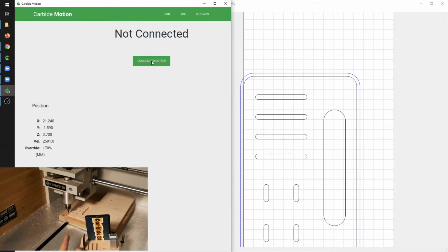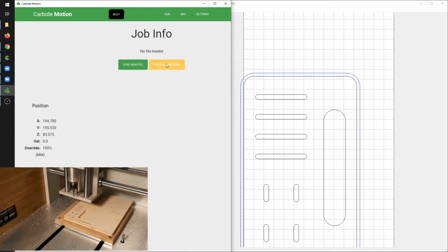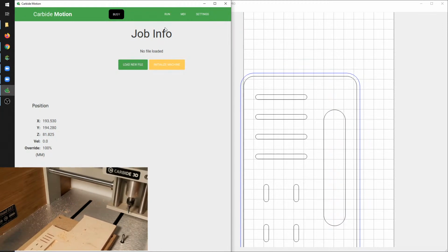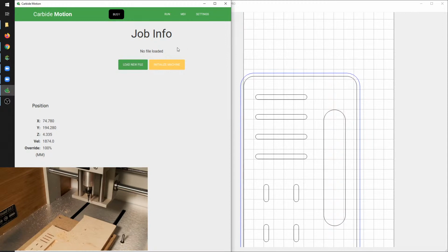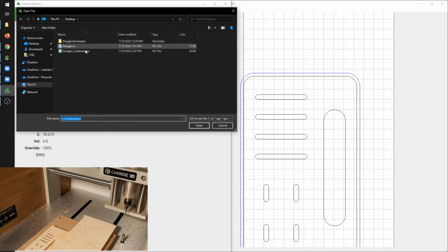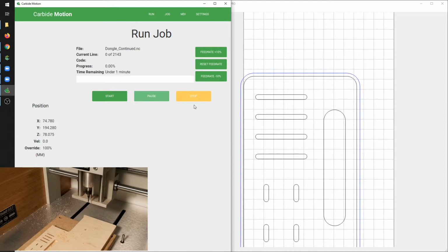And then we'll reconnect to the cutter. There's a current overdraw protection, so when the spindle stalls out, it just resets the controller. I'm actually pretty impressed it made it that far. Okay, so it's reinitializing. It's going to ask me for the tool. Check. And while it's going, I'm just going to load the new toolpath. Start that. Make sure we're back at 100% override.